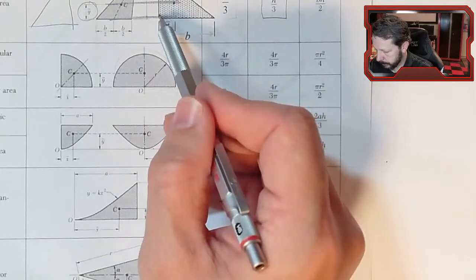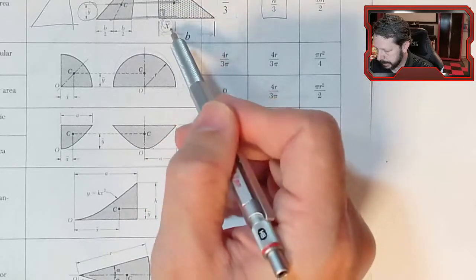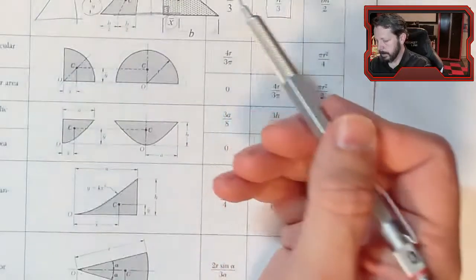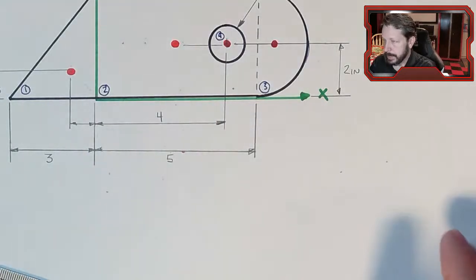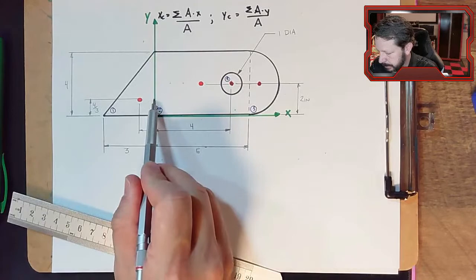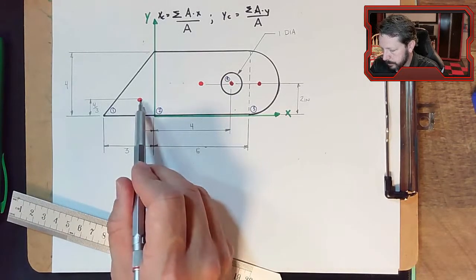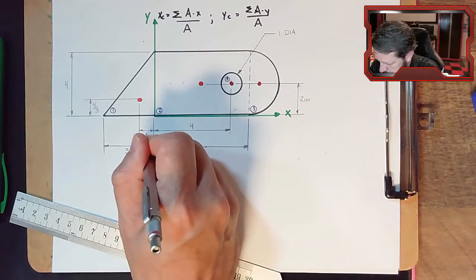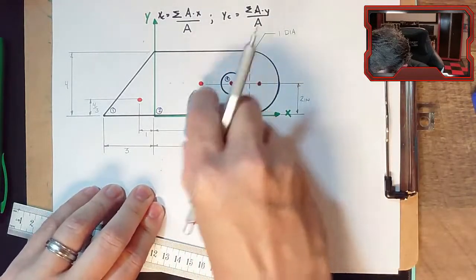Here they're measuring from the right angle over to the centroid and saying that that is the base over 3, so 1/3 of the base. And that's what I labeled here because I want to measure from my y-axis. It's my reference point, so I want to measure from the y-axis over. So that's the right angle over to the centroid, 1/3 of the base. My base is 3, so this is 1. Oh, I don't like that I did those backwards.